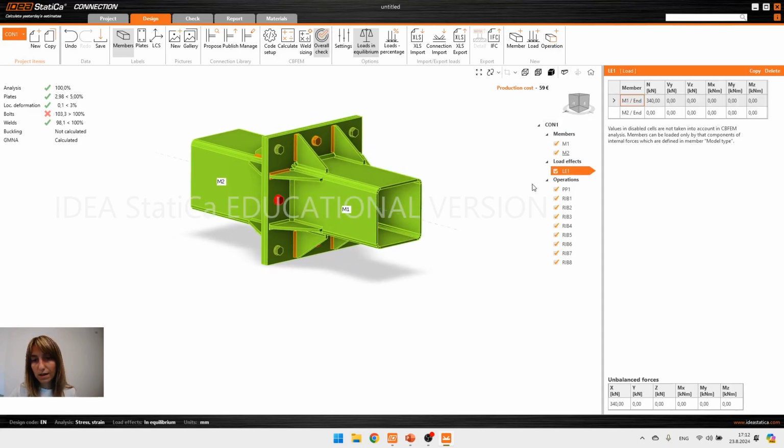And also this example, because this is part, let's say, of a truss, I took one axial force, but the same thing can be applied to a set of forces. Like in example, we can have one axial force, and also we can have a bending moment, and we can have a shear force, and then we can ask the software to run analysis and to give us a factor. Then if we multiply all these forces with this factor, then we will have again the same information about the failure of that connection. So it's applicable also not just for one force, but with a set of forces as well.